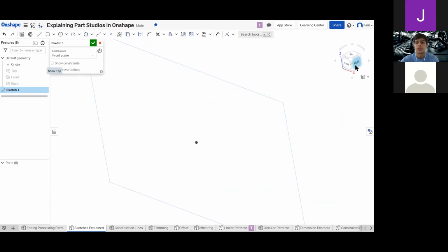Basically you can click front, right, back, or bottom, whichever you prefer. And also, since I'm a hotkey type of person, Shift 1 through 7 are the basic views. I'll go over those real quick. Shift 1 is front, Shift 2 is back, Shift 3 is left, Shift 4 is right, Shift 5 is top, Shift 6 is bottom, and Shift 7 is a view called the isometric view. You can also click some of the corners in the cube in order to switch your view however you want.